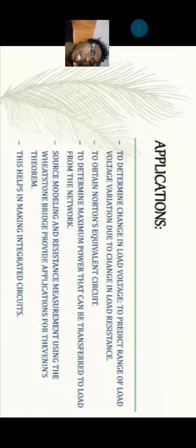Okay, applications. Thevenin's theorem is used to determine the change in load voltage, to predict a range of load voltage for variations in load resistance, to obtain the Norton equivalent circuit, to determine the maximum power that can be transferred to a load from a network, and for source modeling and resistance measurement. The Wheatstone bridge is also one of the applications of Thevenin's theorem. This helps in making integrated circuits.